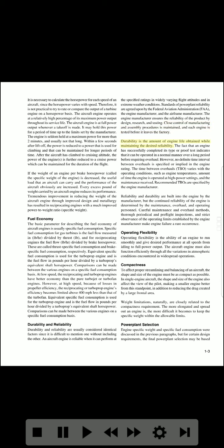Durability is the amount of engine life obtained while maintaining the desired reliability. The fact that an engine has successfully completed its type or proof test indicates that it can be operated in a normal manner over a long period before requiring overhaul. However, no definite time interval between overhauls is specified or implied in the engine rating. The time between overhauls, TBO, varies with the operating conditions, such as engine temperatures, amount of time the engine is operated at high power settings, and the maintenance received. Recommended TBOs are specified by the engine manufacturer.